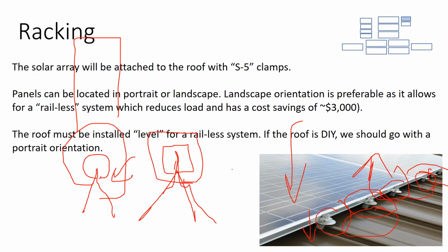And so we had 8 rows of modules. The rooftop going across the roof was about 10 modules of about 5 feet each, so we're going about 50 feet. And so every 16 inches, that's a lot of time on the roof, bending over, crimping, and putting the rail on.